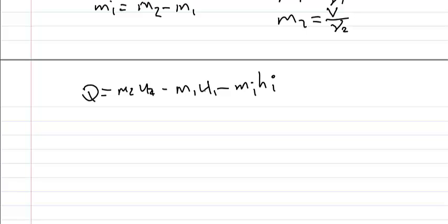Keep in mind that this is only a single inlet, right? There's no exit streams, just an inlet stream, so this is the appropriate equation. Let's also note that like essentially all of these charging and discharging problems, there's not going to be any mechanical work. There's no mixing devices or shaft work or anything like that. Also, there's no kinetic or potential energy changes associated with any of the substances in this process. So that all gets neglected. That's typical of all these types of problems.